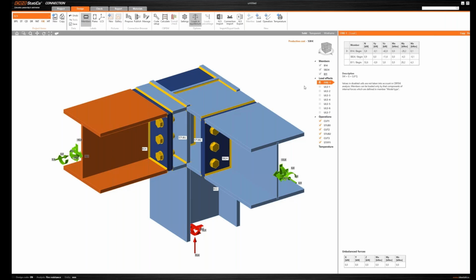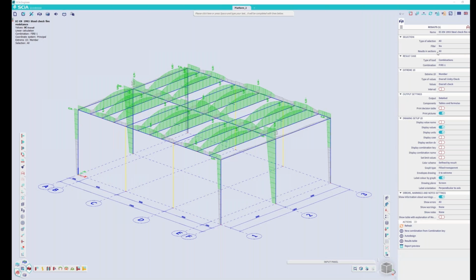Now at this point, we need to define the material temperatures for the fire design condition. However, these are calculated in our global analysis software. So we need to move back there, identify the corresponding members, and check the calculated material temperatures in the report.